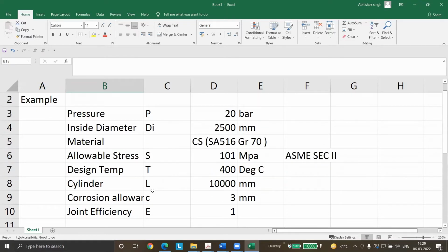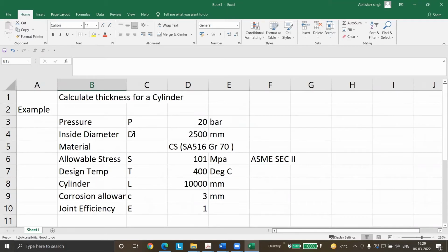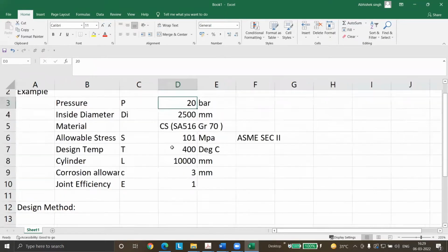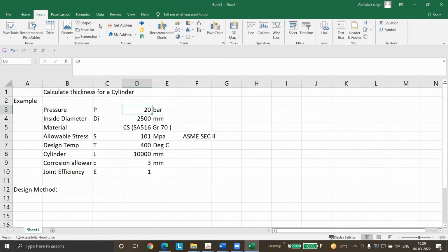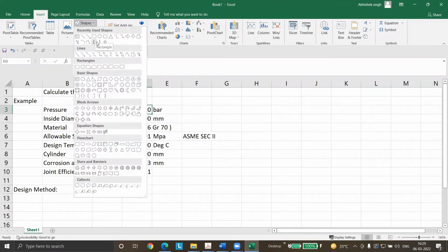You have not studied the code till now, so what formula are you going to use for calculating the thickness which can take care of this much pressure? Yeah, rightly, the circumferential stress. That is the reason we learned circumferential and longitudinal stresses, right? This was the purpose for doing that.